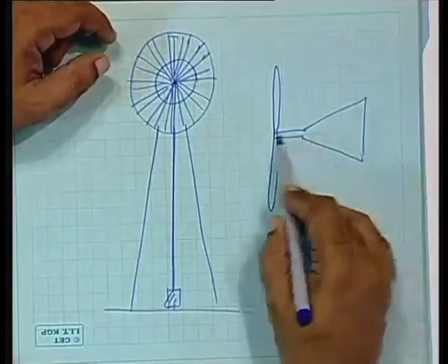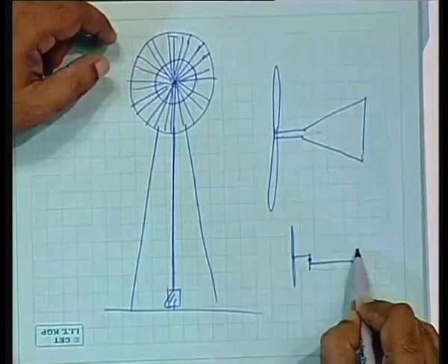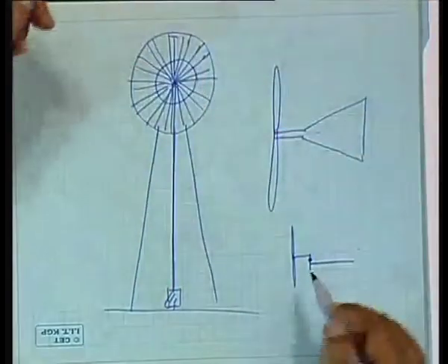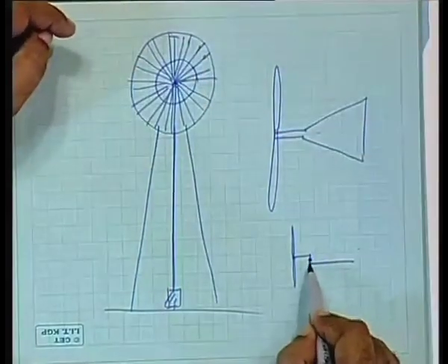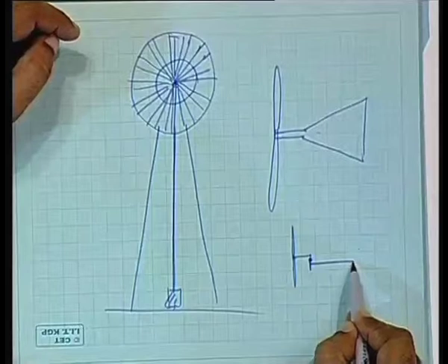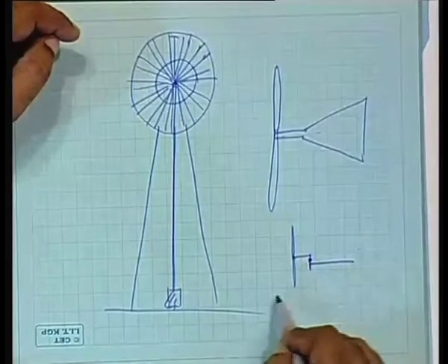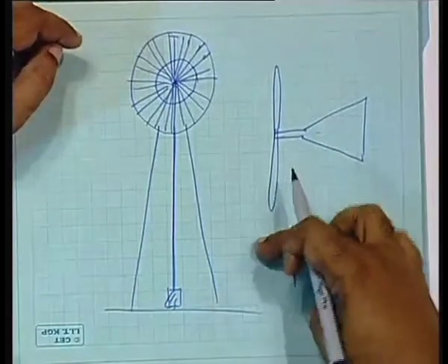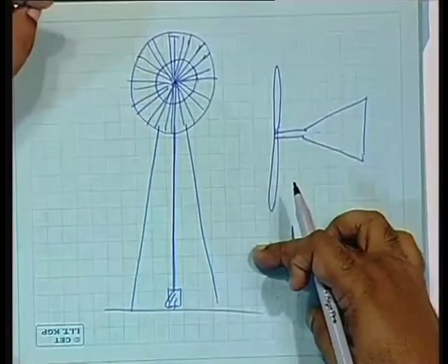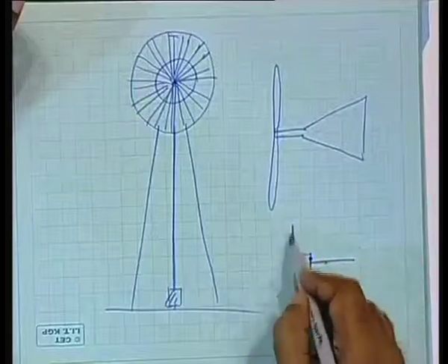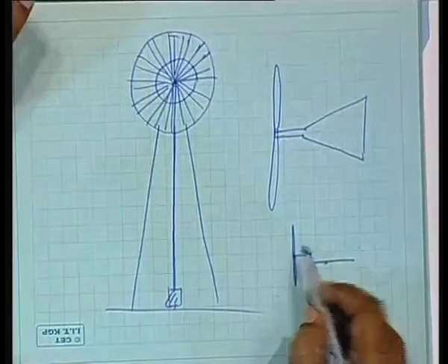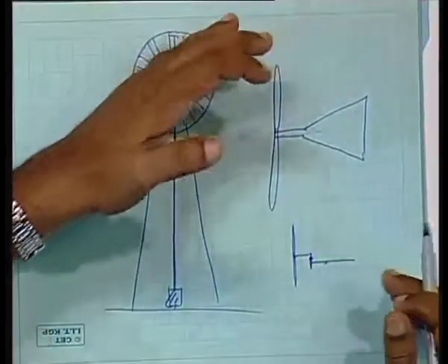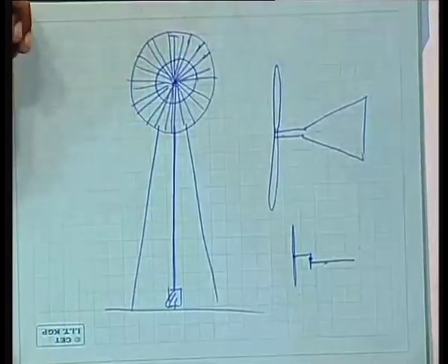Earlier you'd think that this is in the same direction, right? If you look from the plan view, then it is not really in the same direction, slightly off. As a result, when the wind speed is less, then the force on this one dominates, and it orients it around the direction of the wind. But when the winds are large, then the thrust on the blade will dominate, and it will disorient it away from the direction of the wind.